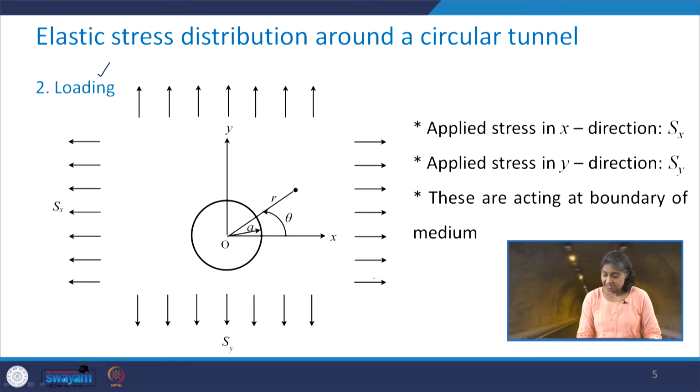In the x direction, this is Sx, and in the y direction, this loading is Sy, and these Sx and Sy are acting at the boundary of the medium. That means that they are far from the circular tunnel. And what is the boundary of the medium? That we consider to be semi-infinite medium. So, practically these stresses are acting at that large or infinite distance.